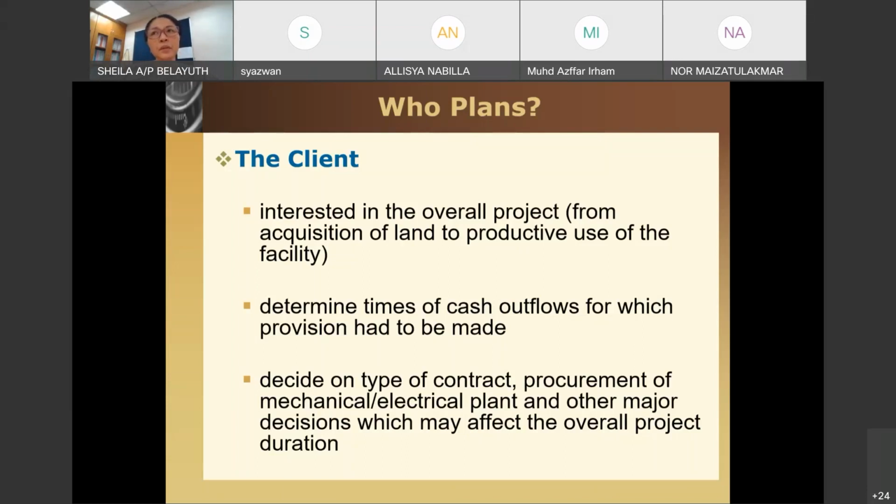So for example, if your electrical items, your conduits and so on, basically they are embedded in your slab, because you don't want superficial conduits. You don't want all these electrical piping running on your wall. If they are embedded, then it needs to be done before you concrete the slab.